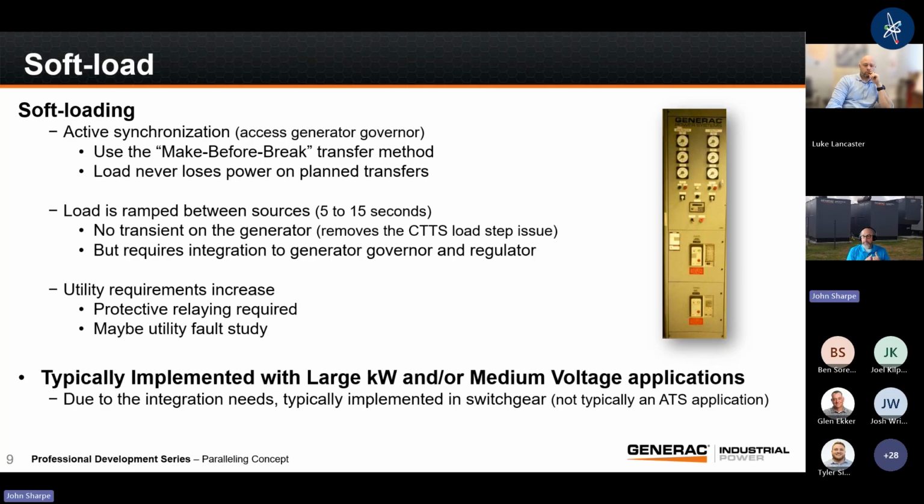Okay. Now, that is a closed transition momentary under 100 milliseconds. However, sometimes this transition is a bit challenging for the generator or for the utility. We think about this, right? I'm transferring between two hot sources. So maybe I've lost power. I'm on generator. Been on generator for a couple of hours. The building's back to running perfectly normal. And now I need to transition back to utility because the utility's come back. Okay.